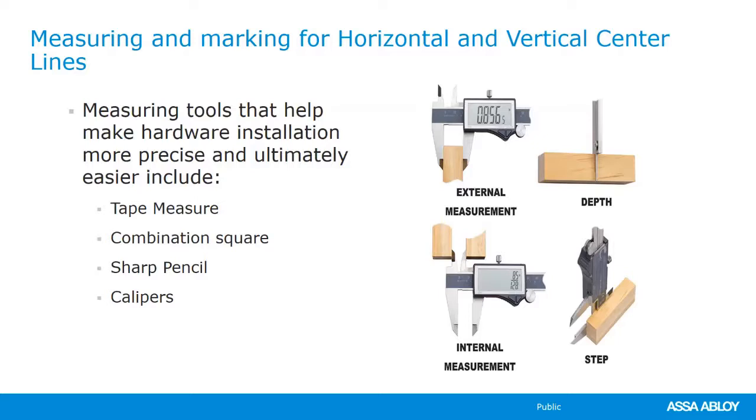Now, I guess you could take a pencil or something like that and just stick it down into the hole and hold it and then measure it with a tape measure. But using the depth measurement for the calipers is just, to me, faster and more accurate. But one of my favorite ways to use a caliper is the step measurement.